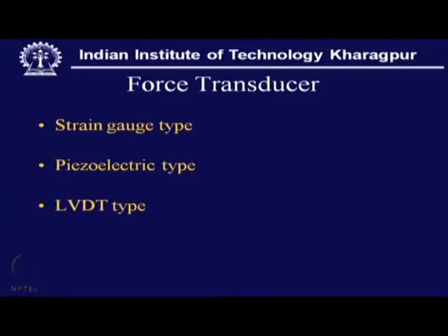It can be LVDT type, linearly variable differential transformer, or piezoelectric type sensor or transducer that can measure this friction force with the highest possible precision, capturing data which will be very useful for analyzing the whole performance of the coating.